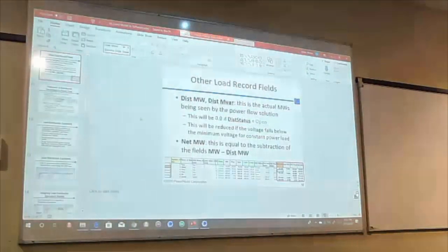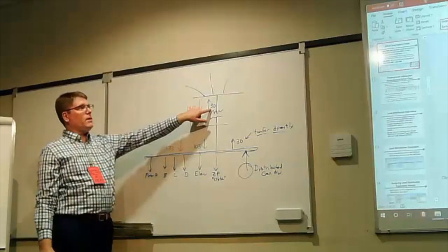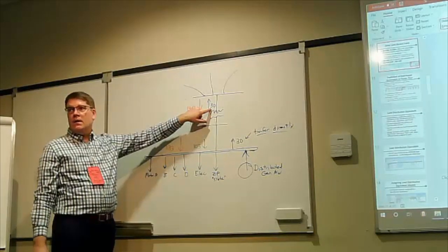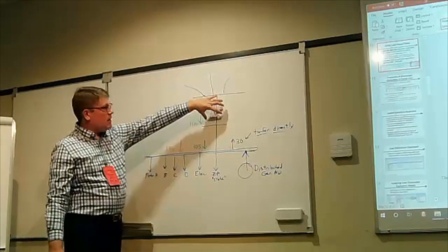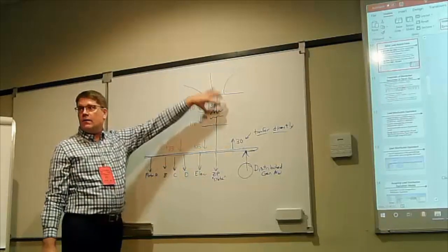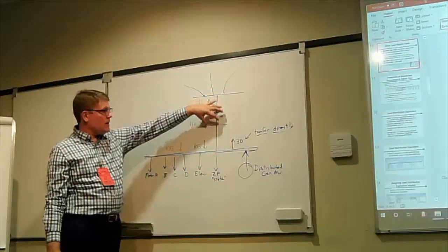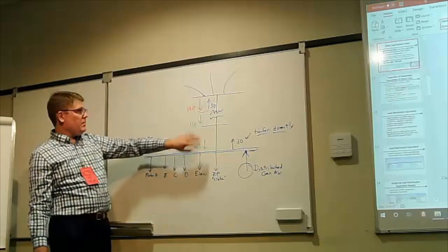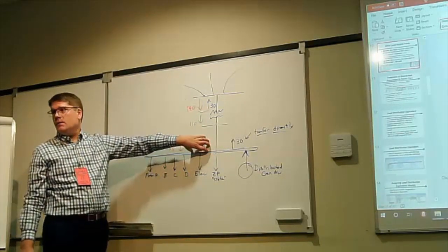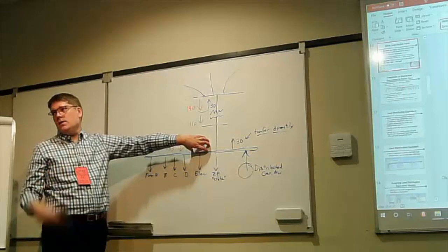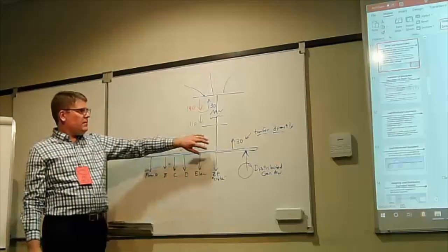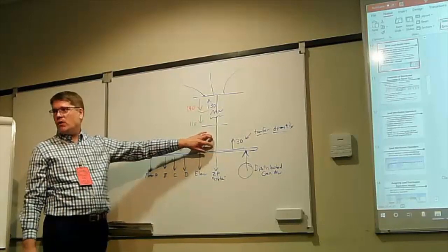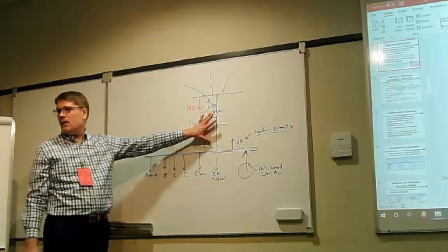So when we initialize this model, if we start with 140 megawatts of load and 30 megawatts of DER, then we've got a net of 110. So we're going to calculate, because this has an R and an X and impedances, inside Simulator how much power makes it all the way down here to the end of that feeder. That's part of our initialization. We will calculate that. There's usually 5% loss or so.